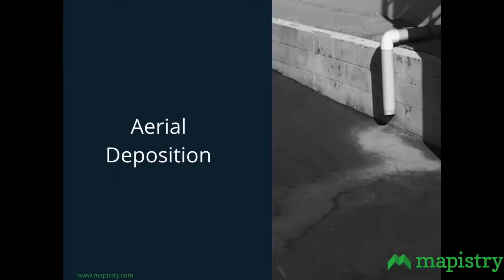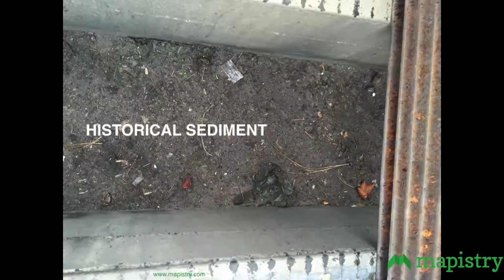The other thing is aerial deposition. If you live in an area where there's mining or processing of sediments, aggregates, sands, gravels, rock, or if you just live in a windy area, high desert, other areas where wind-blown sediment silts can show up on your site. They can show up on your roof and then come down a downspout like you're seeing here, the staining. It's accumulating on a roof, and then once it rains, it comes out that pipe as a concentrated form of TSS.